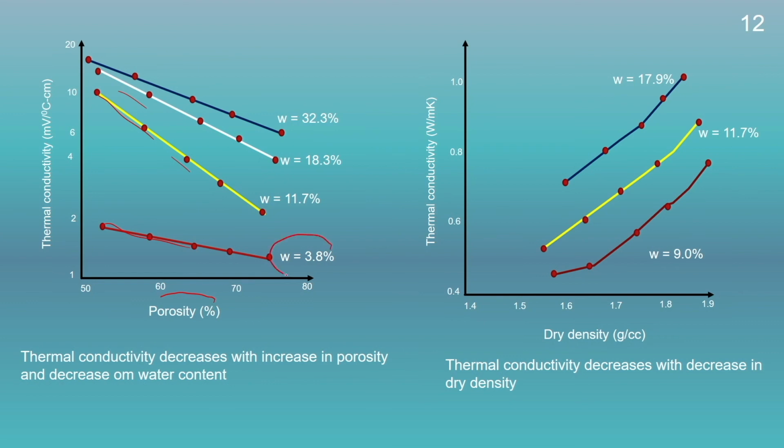As we increase the water content, the amount of water present in the pore space will increase. So, for any porosity, as we increase the water content, the amount of water inside the pore space also increases. As the amount of water inside the pore space increases, the convection phenomenon will also increase, and that will increase the amount of heat transferred through the soil.